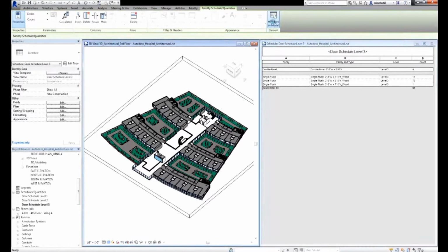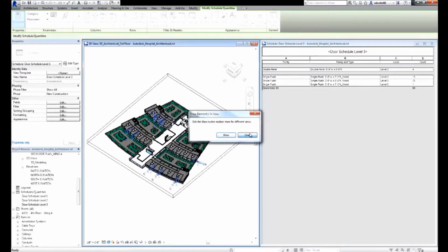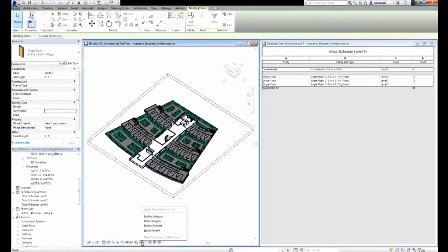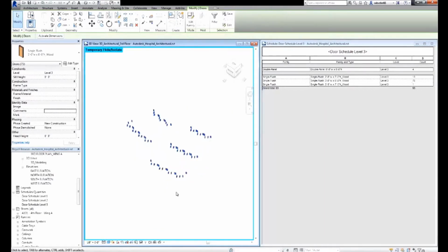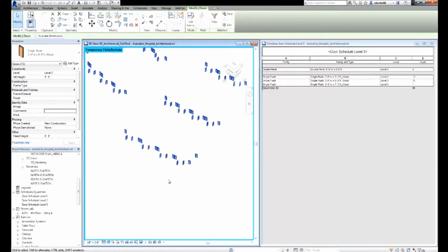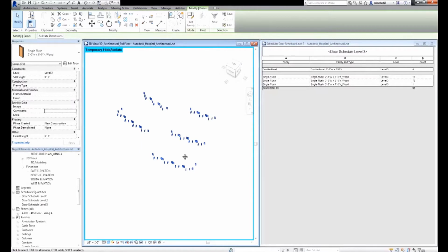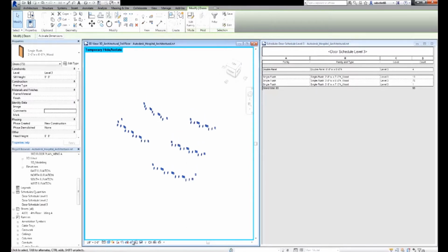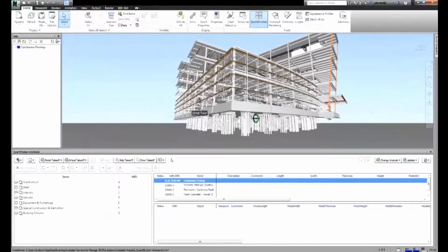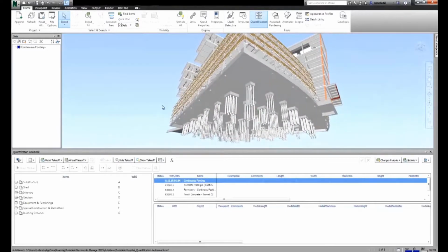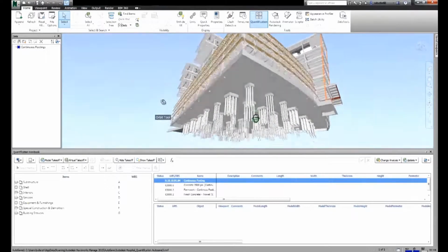Here we can see how the Autodesk solution provides several ways to gain access to the quantity information early in the planning process. By leveraging tools directly from Revit and NavisWorks, we can quickly get a high level of understanding of the project quantities. Schedules or tables of data built from the 3D model created by the designer can be used by adding counts and totals, or a custom table can be generated on the fly to give you feedback and quantities from the model information immediately.